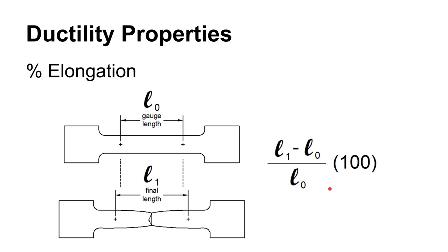So we bend a piece of sheet metal or a piece of wire. We are using the ductility of that material. So if we have a material that does not have much ductility, we're not going to be able to bend it without breaking that material. If a material is ductile, that means it can flow nicely. So there are a lot of processes that require this, like extrusion and bending, things like that. So we want to determine the ductility of a material. These are some good ways of doing that.